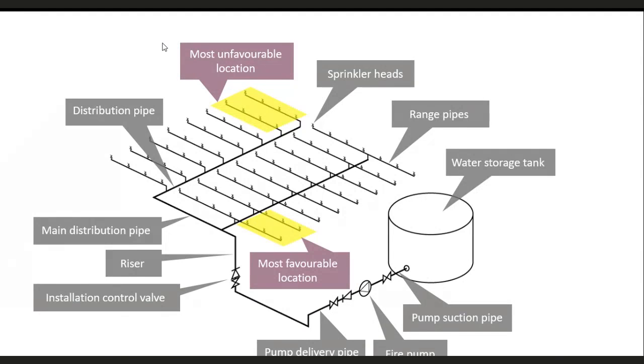Also, the most favourable location, and I say that is to do with the water storage tank, because the worst case scenario as far as the pump is concerned is the most unfavourable location. The worst case scenario as far as the tank size is concerned is the most favourable location. There's going to be more water coming out of those heads, therefore we need to allow for the duration factor.